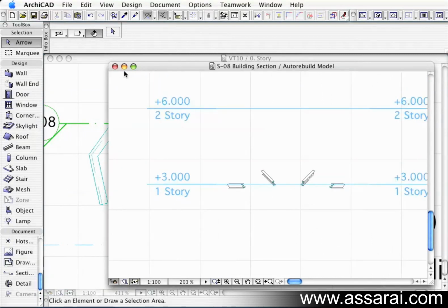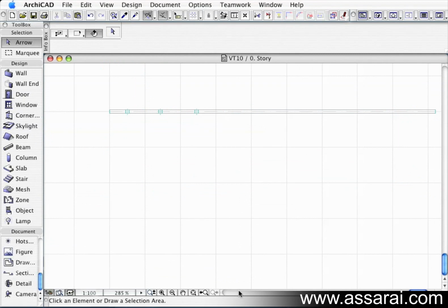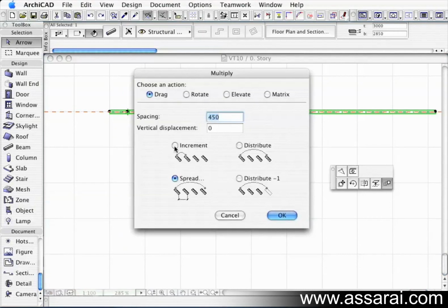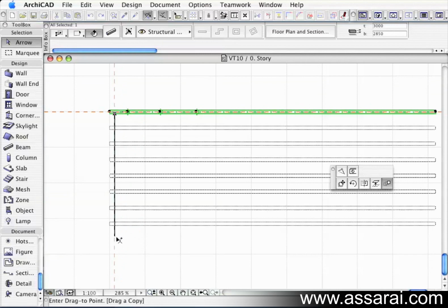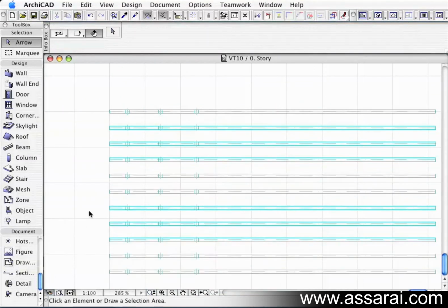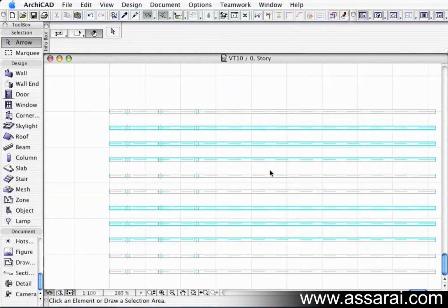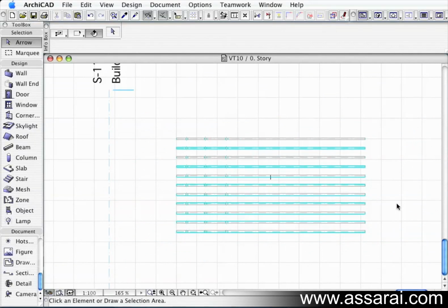using these tools. It's probably worth noting that rather than drawing a 2D element in a section or elevation, it's far better to model everything in 3D, including all your beams. We've got advanced tools to do this now, and the obvious byproduct of this is that all our documentation can be coordinated. So it's very simple to do all your sections and elevations, and you just know all your drawings are going to be right if it's modeled correctly.